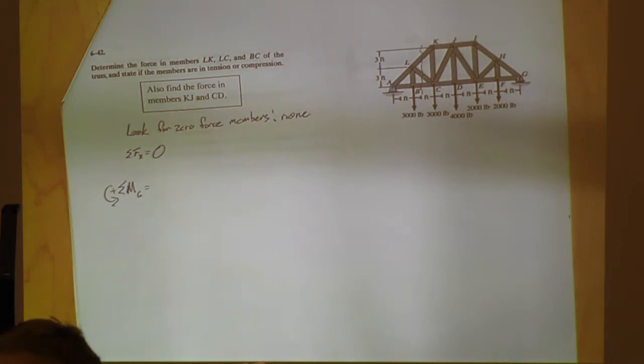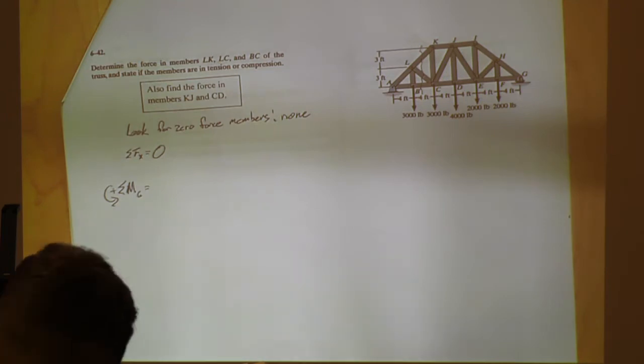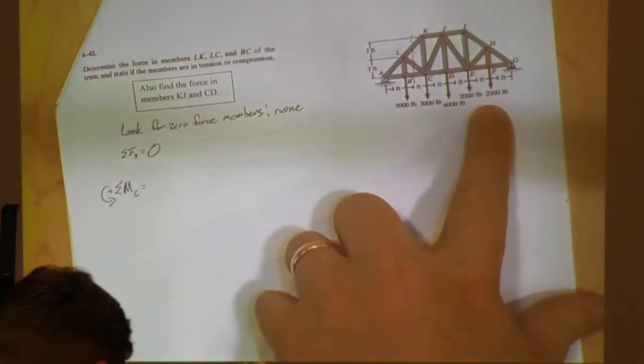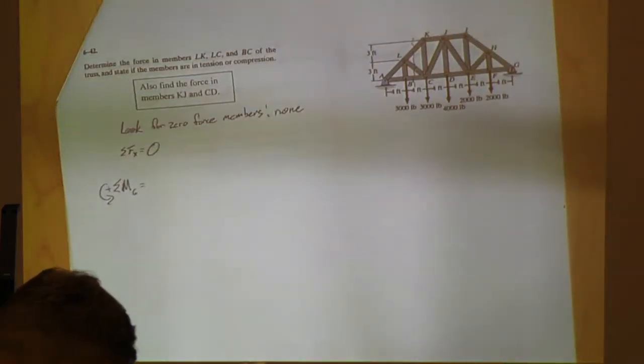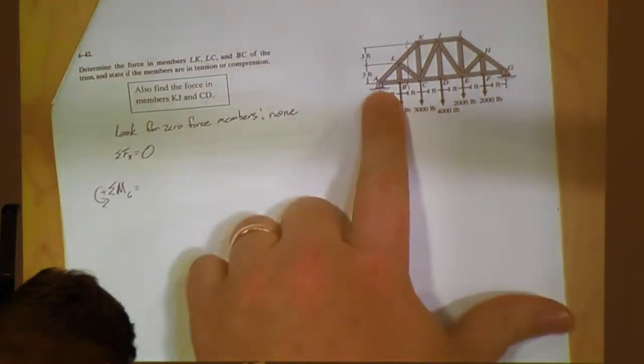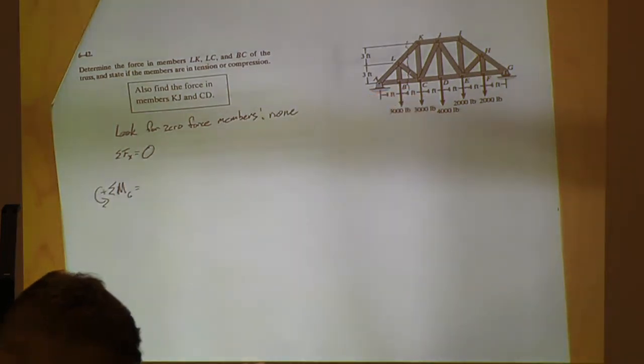So what do we do when we calculate the reaction forces on a truss? We're treating the truss as a rigid body, so all we're taking into account are the external forces on the truss. What are the external forces? We have these, 5 down here, and the reaction forces are the externals. Since there's no other thing besides the x reaction force, we're in equilibrium, so AX would be 0 because there's no other external force to react to. Make sense?